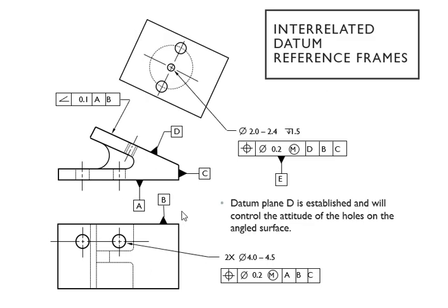So for the attitude of the hole, which is this one right there in the auxiliary view, you can see that with 45 degrees. Don't forget it on the views, please. That's the third control frame right there, and your primary is going to be the datum right here, and it's going to be controlling this little circle right here, and the tolerance is 0.2. We need a maximum material condition, and here also maximum material condition for that circle right here.